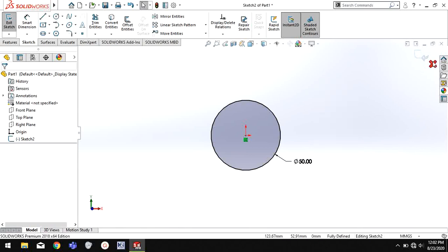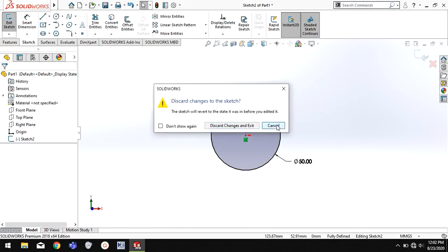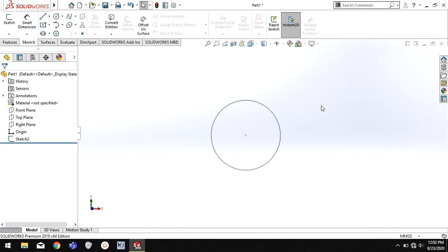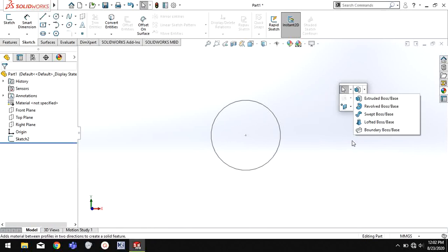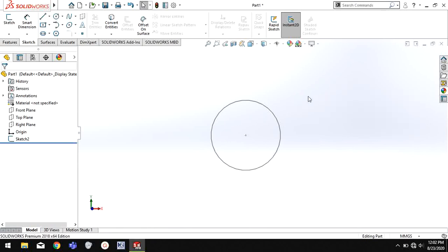And if you're not in the sketch mode, then if you press the S key, you will get the tools which you use for the feature tools. Right now none of the sketch is selected, so that's why I'm not getting anything else. The only option for you is extrude. So you are getting the extrude and you have all the extrusion options available.